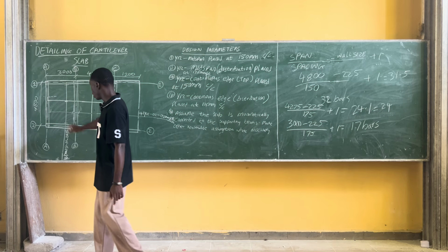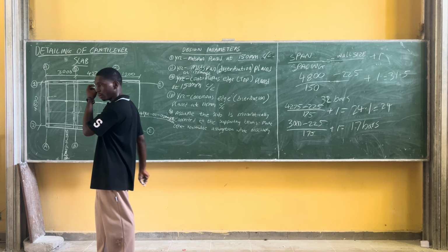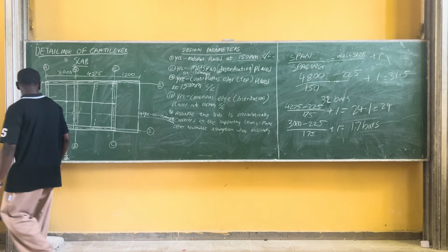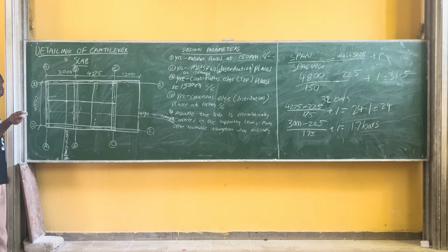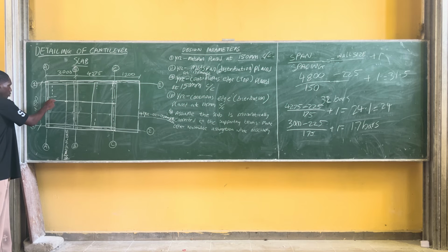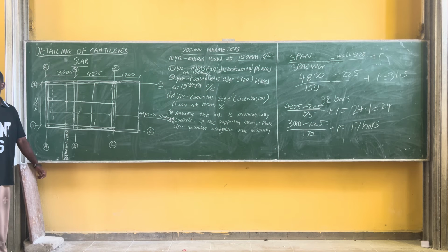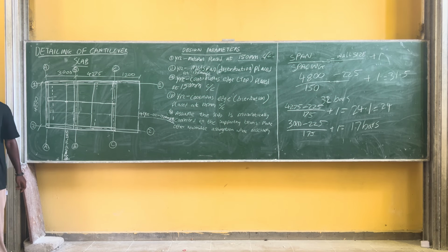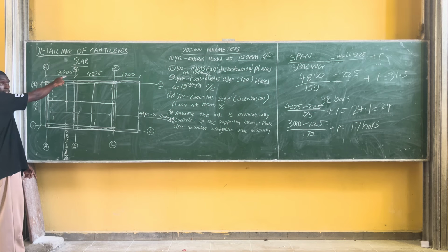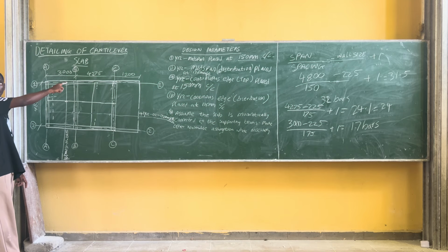Now what we're going to work on is our T1 and our T2, which are top bars. How you're going to do it is, this is only one here. Normally, when you're drawing your top bars, always make sure it's dashed lines. And I'm putting a dashed line in between this hook here. Now, Bronson asked me a question: what is the span of this hook? It is 0.15 times the span, which is this 3,000. Yes, when you're getting the hook.